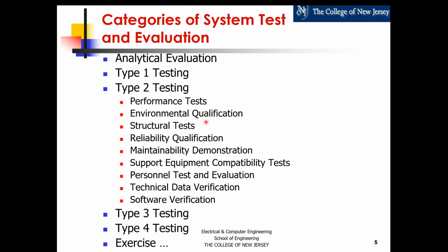So I did also, all this is here: environmental, structural tests, reliability, qualification. They're sort of in my mind, they're bunched up together. Also, I mentioned drop test. So you want to know if this product is packaged as is intended to be shipped, and the UPS guy drops it from the truck. Is it going to break, or is it well protected? So all these tests you do as you ramp to production.